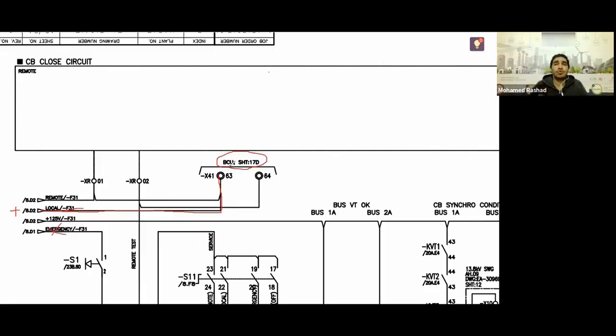You can control opening and closing at the same time. You have an energy meter from which you can take readings, and you have an annunciator, a bit small, taking the alarms present on the station side, but in the form of aggregated alarms. All right, very good. What did he do? He told you to skip this control room. I will do something very simple. I will bring an IED, an intelligent electronic device, and install it in my cell, in my panel, in the LCC panel itself.